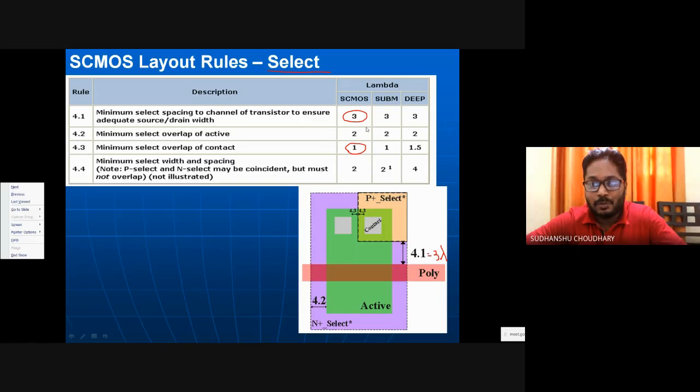When somebody wants to optimize the performance, that is, somebody has very stringent performance metrics that have to be met, then obviously one has to play with these design rules. That is, one has to tweak these dimensions and make all of them minimum. If these dimensions can be kept minimum, then the size of the layout can be small, and obviously the size of your IC, that is the wafer utilized for fabricating the IC, would be small. So you will save some money for the company also.